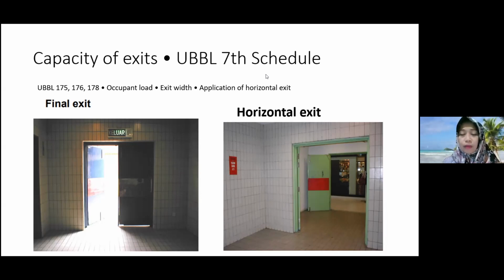Because you will design your gallery, and how the people, maybe from a small auditorium or small exhibition, get to outside, meaning that you are providing the final exit. But if the upper area goes down and your staircase is allocated slightly at the middle, make sure those exits, which we call horizontal exits, are straightforward.